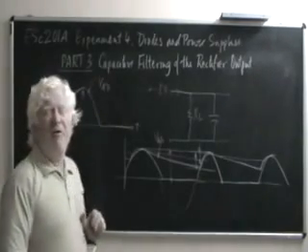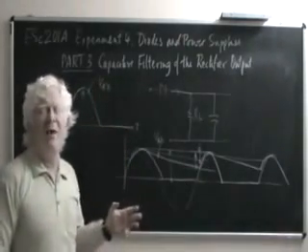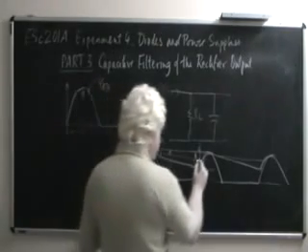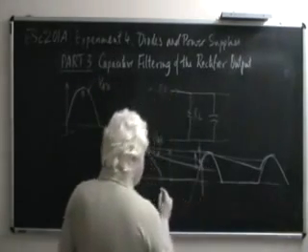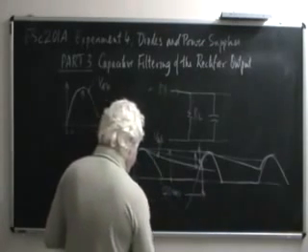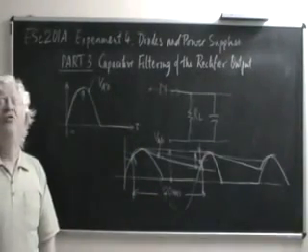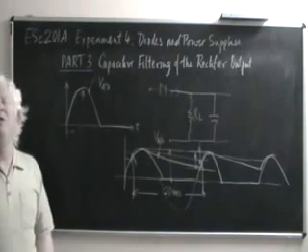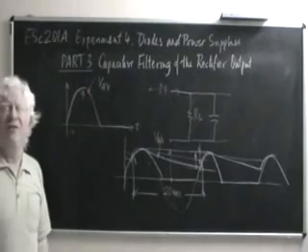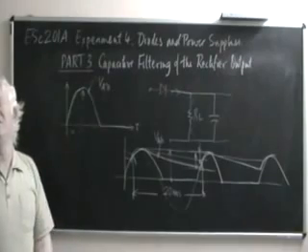And in the case of a half wave rectifier, those two times are one cycle, one period apart. With a 50 Hz supply, that means this point and this point are 20 milliseconds apart. Whereas, if you used a full wave rectifier, they would only be 10 milliseconds apart, because at the very next half cycle, instead of the next alternate half cycle, you would again get an opportunity to charge the capacitor.